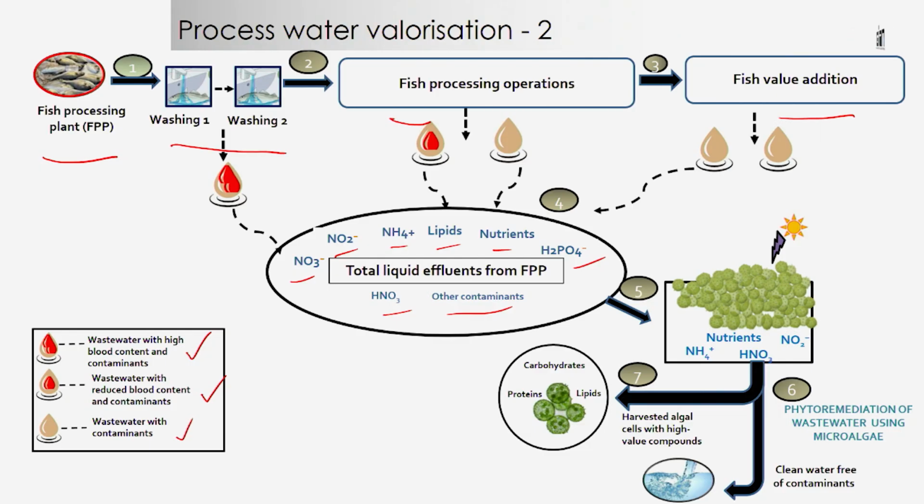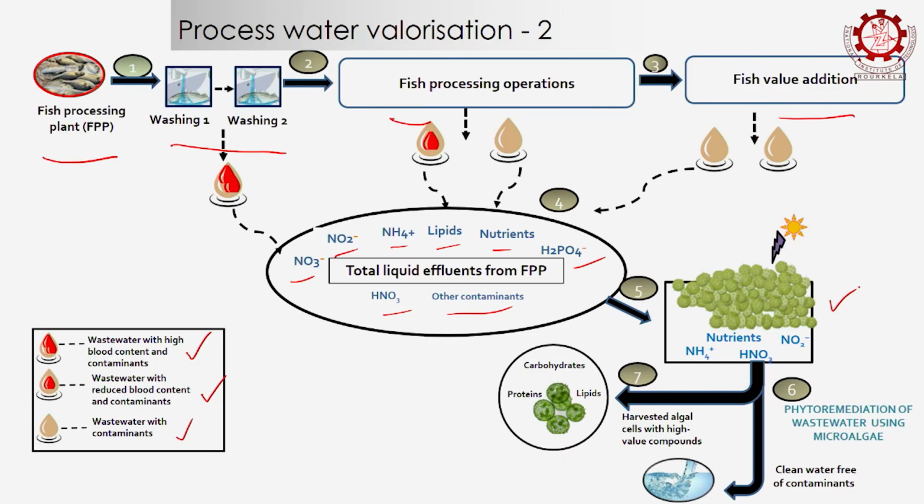So before you start a valorization strategy for a wastewater, you need to understand what the contaminants in the water are, what the condition of that water is before you start extracting. Yeah. And then with all these nutrients, whatever is there, you decide whether you want to propose a system to grow macroalgae, microalgae, duckweed, or any other plant which can absorb these nutrients, and at what rate.